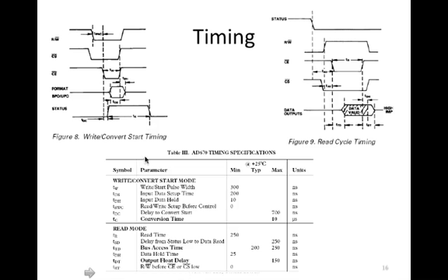Now, one example you probably cannot see very clearly: between this dashed line and the rising edge of this status, this small gap here is what's called TDC, where DC is the subscript of this symbol. This is the delay to conversion. It's the time that it takes for this chip to respond to the control signals before it actually starts doing the conversion.